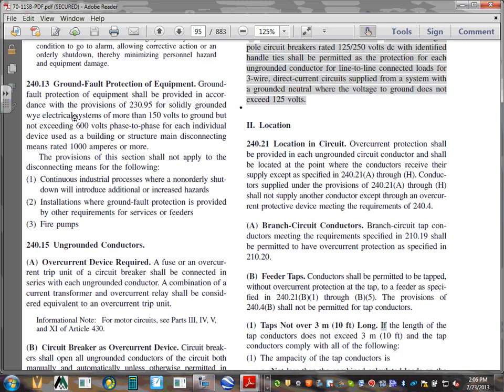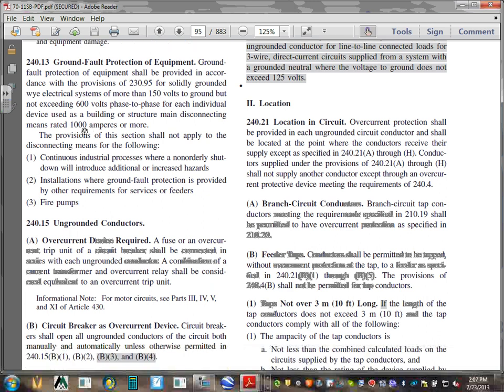Ground fault protection, I'll talk about ground fault protection. This also becomes a very big deal. The NEC code book requires, with 3 exceptions, if your circuit breaker is very big, meaning 1000 amp or higher, and if your system is 480/277 or 600, you must provide ground fault protection on the feeders or the branch circuits. At the 1000 amp or higher level, the ground fault becomes high enough to be destructive and burn equipment, but low enough that it cannot be sensed by the CTs on the phases. So they require you to provide protection.